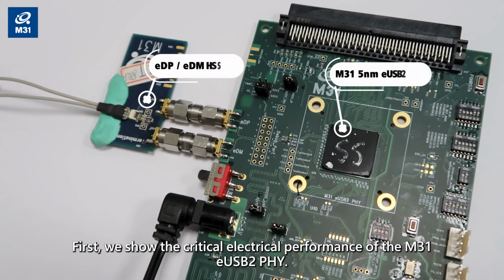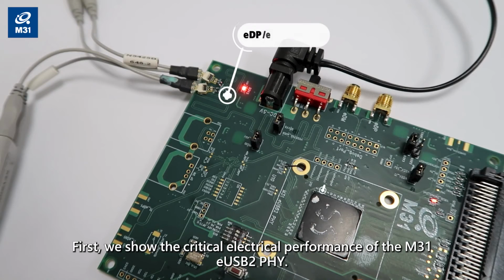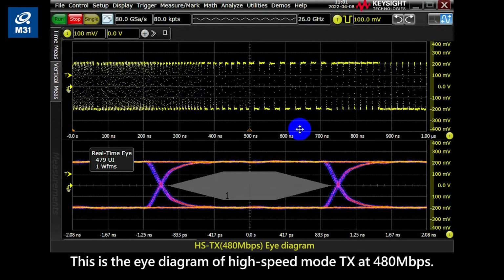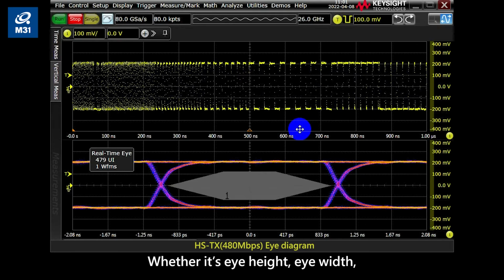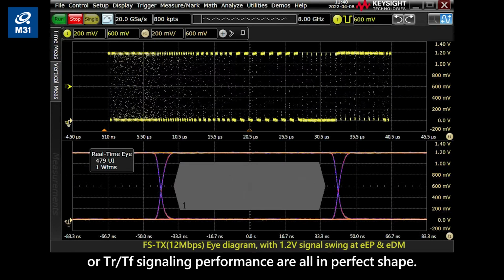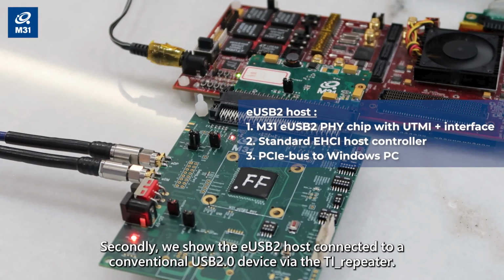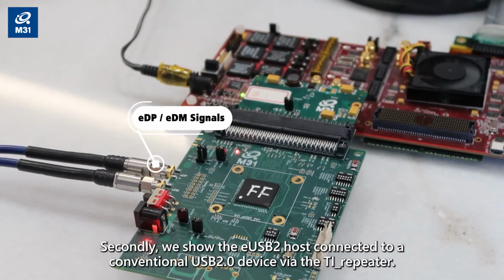First, we show the critical electrical performance of the M31 eUSB2. This is the eye diagram of the high-speed mode transmitter at 480 megabits per second. Whether it's eye height, eye width, or TR/TF signaling performance, all are in perfect shape. This is really amazing.